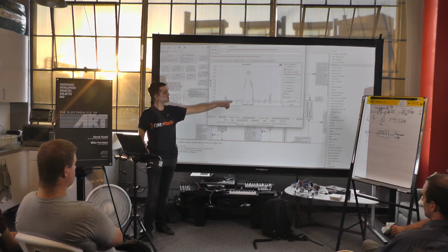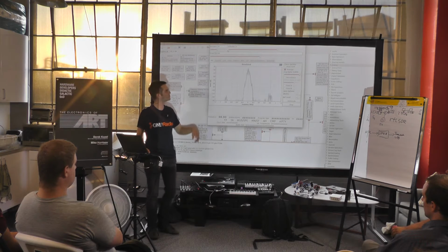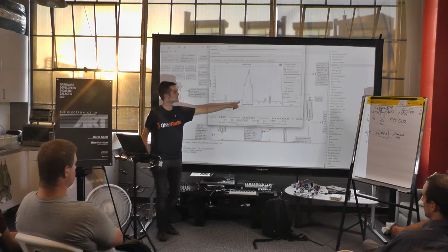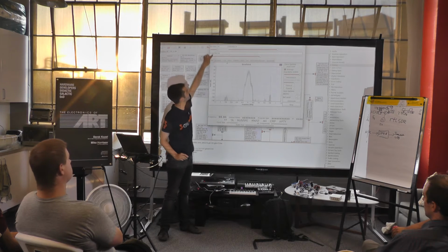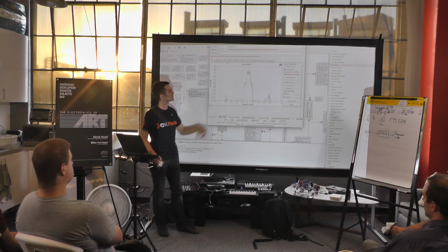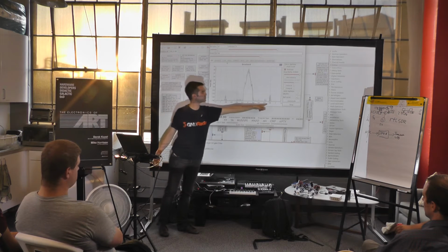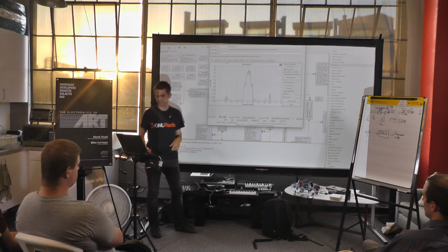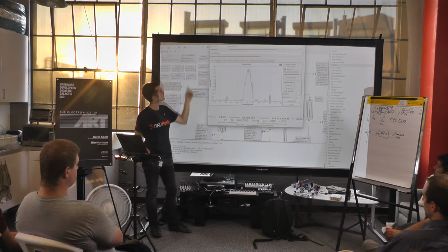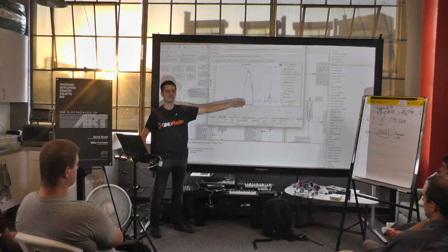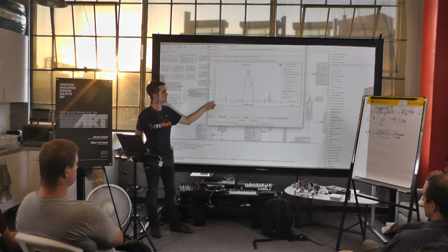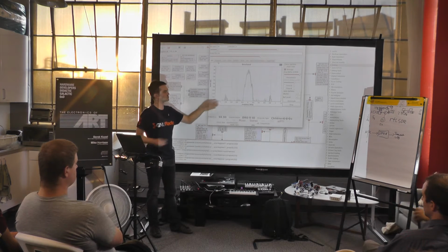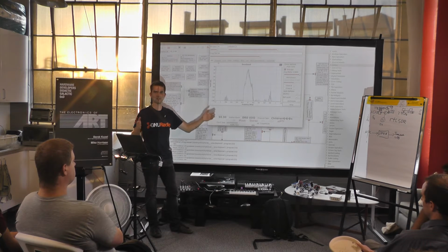So here we have our same Mexican radio station that we're receiving. We can see there's a very strong signal right in here. And so we're tuned to 98.9 megahertz. Got your strong signal here, but then there's also some information out on the side there. So if we start working through the tabs, this is called the baseband. This is your basic signal. And right now we're looking at a width of 2.4 megahertz, which is much wider than your actual broadcast FM signal.